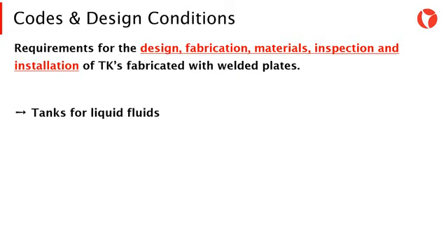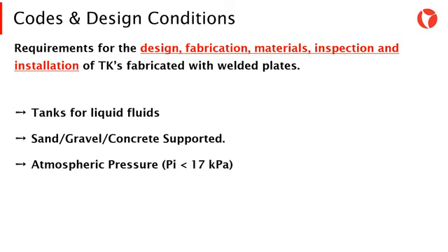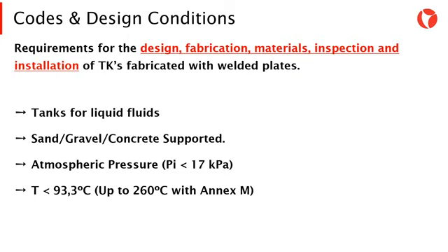Tanks can only store liquid fluids. The bottom of the tank must be sand, gravel, or concrete supported. The internal pressure in the tank must be lower than 17 kilopascals, and the operating temperature has to be lower than 93 degrees, going up to 260 if Annex M requirements are met.